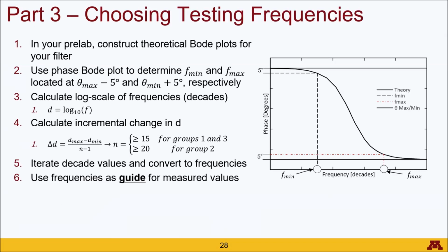So the first thing that you'll want to do is to figure out what frequencies you'll be testing at. And so make sure that you complete your pre-lab, which instructs you to create a theoretical Bode plot for your filter, both for amplitude and phase.